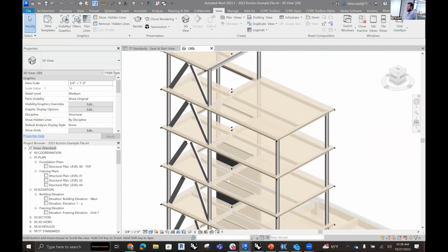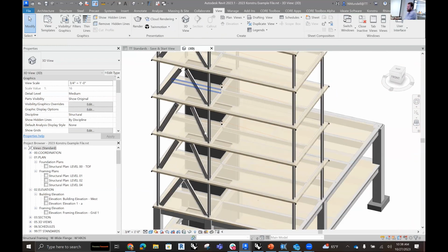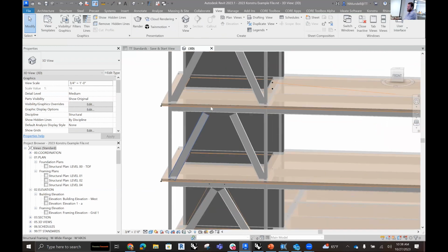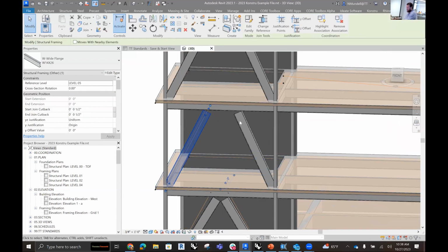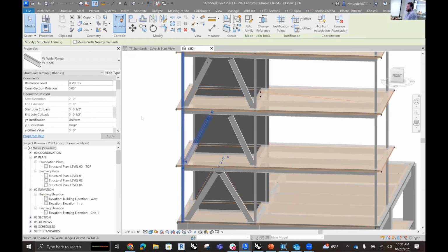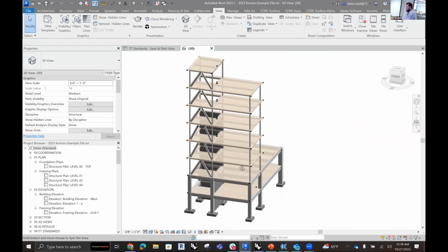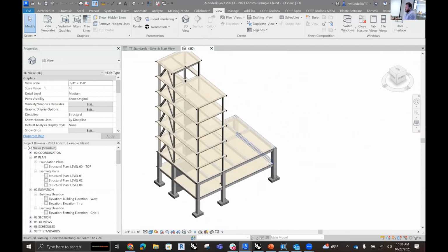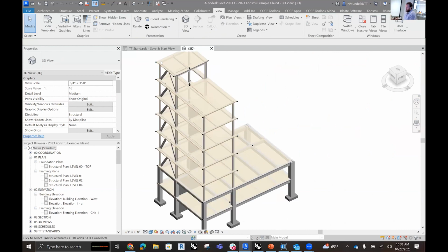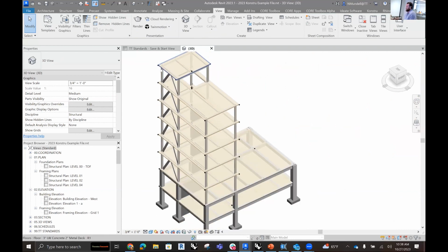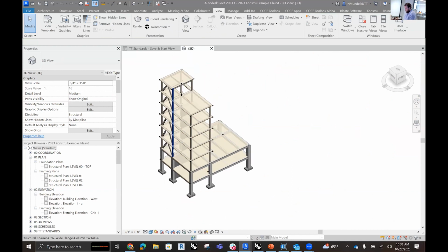In this model, there could be a very good reason why you might want to position the brace here. There could be a doorway, for example. But for the analysis model, we may want that to be connected. So Revit includes two descriptions of the geometry. That's the first thing to understand. Konstru is able to access both.